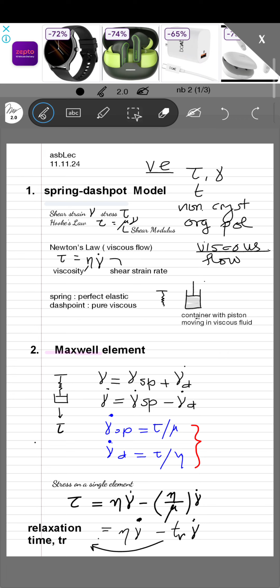It is actually analogous to the creep phenomenon in crystalline materials. So, viscous flow is analogous to creep, which is found in crystalline materials. In crystalline materials, the property is known as creep, or the study is known as the creep test, whereas in the case of non-crystalline organic polymers, it is called viscous flow.